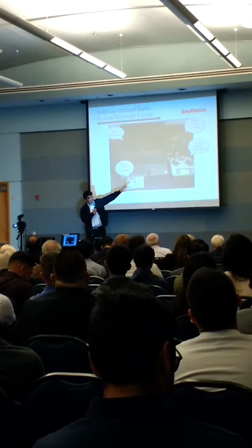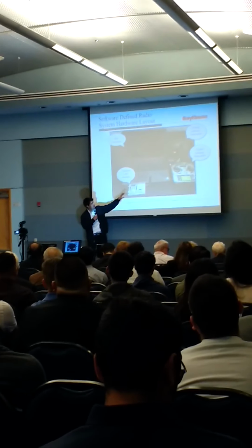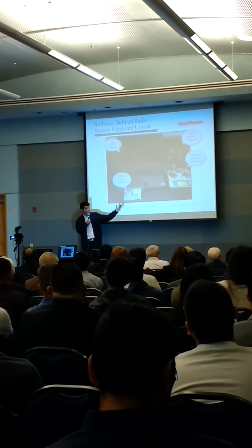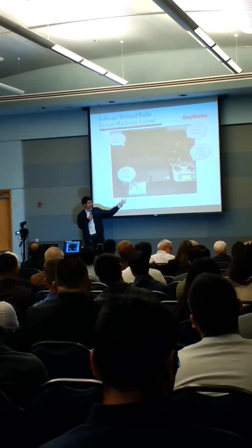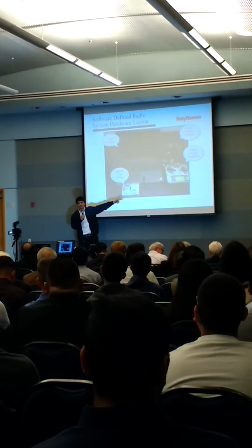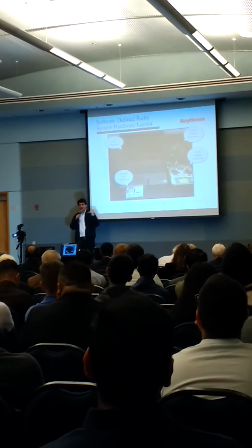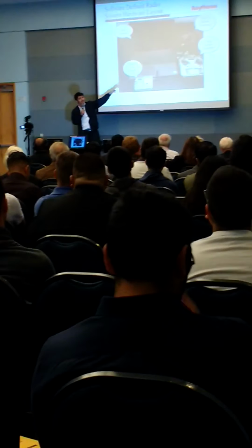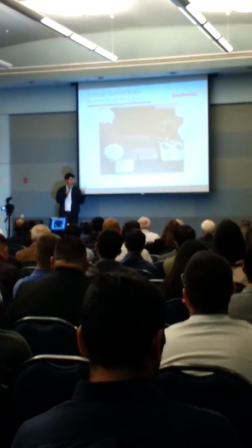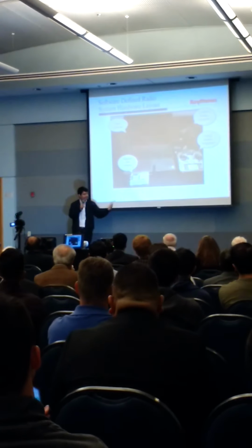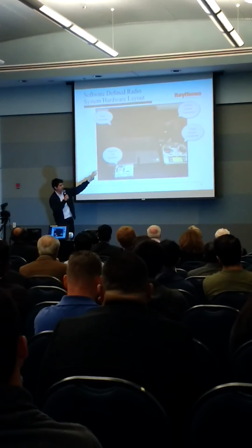And over there are our sources. Those are some controllers. When those things turn on, we're trying to detect them. When they're on, we want to sound an alarm. So that's the 72 megahertz controller. That controller outputs a constant 72 megahertz signal. Then we have the 2.4 gigahertz controller all the way at the left corner, and that outputs spread spectrum, so the signal is sent over many carrier frequencies, not just one. So that one's a little bit trickier.